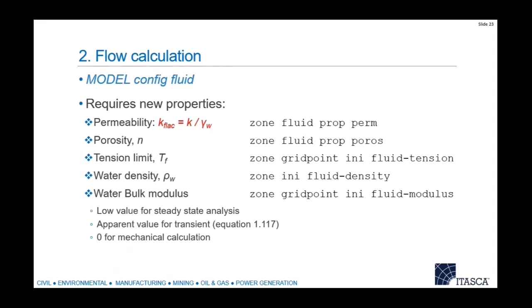All right, now we want to do the full fluid calculation. Let's say that we didn't get that water table, and we're not sure where the water table is. And actually, it turns out if you do the full calculation, the water table does not show up where that surface is, which is what a simplified analysis would give. The pore pressure distribution, you get R a little different, right?